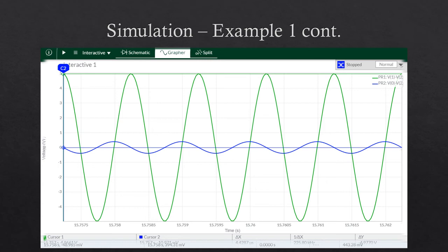As we can see from our theory, this is in line with what we expected. The op amp is clearly integrating the circuit here. As you can see, we have a cosine wave for the input from this point, which gets turned into a negative sine wave, as we would expect it to do.